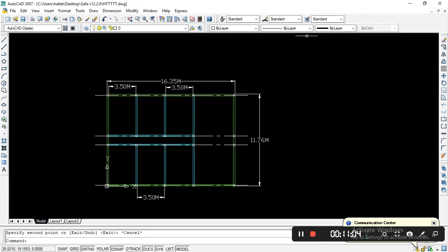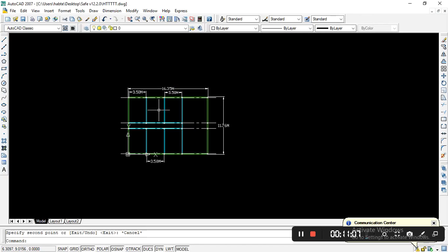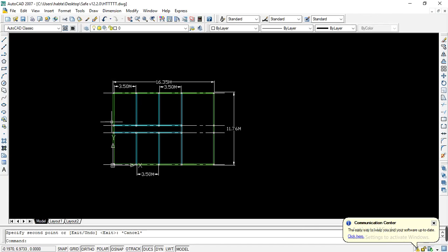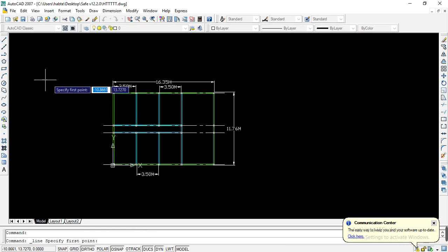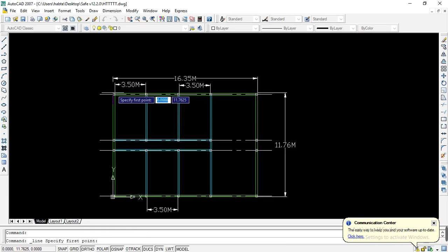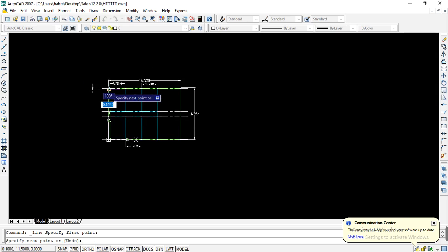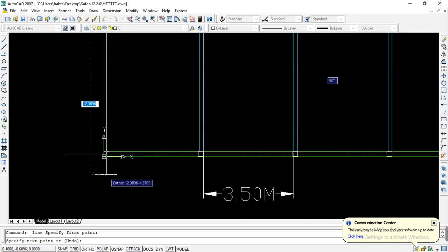Okay, fine, guys. Here, the next thing that I'll do is, I'm gonna put the vertical grid line here. Then after that, I gotta copy it horizontally. So I'm selecting the line symbol or the line object. Then, as I told you before, I'm gonna draw a line. Okay, a grid line here. So I'm coming vertically down here, and I can finish it here.